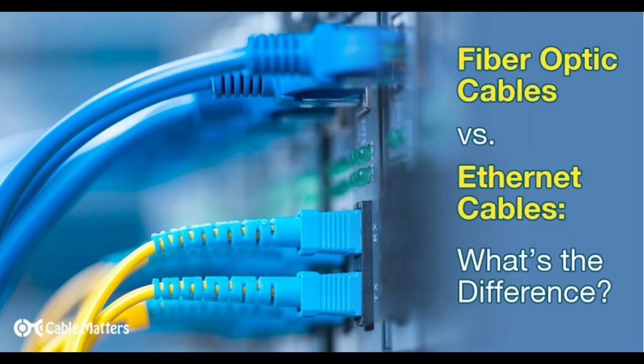The light signals used in fiber optic technology are generated by a light-emitting diode, LED, or a laser diode. The light signals are then transmitted through the fibers, which act as a waveguide, carrying the light from one end of the cable to the other. The light signals are received by a photodetector, which converts the light signals back into electrical signals that can be processed by electronic devices.